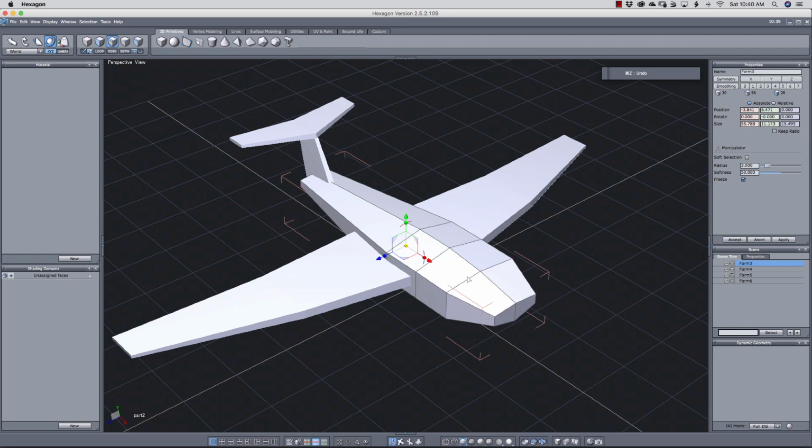When you are modeling this way, never add more detail than you need. If you make unnecessary divisions at the early stages of your modeling, it will be harder for you to add bevel edges. And that's something we're going to go over later in another lesson. Anyway, another thing I wanted to show with the loop selection is that you can change the direction of it by pressing it twice. In surface selection mode, see, it's a toggle.